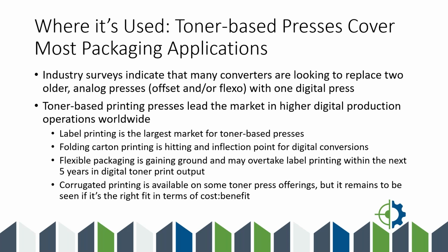The unique thing is, though, with modern toner presses with this productivity, if you have 20 jobs from 20 different customers or multiple SKUs, you can pretty much gang all of those orders, turn on the press, and it will flag and separate each job with a barcode or a marker for an operator to separate the prints. Once you turn it on, you can pretty much run an entire master roll if you've got enough to fill that in a single run where everything is separated. So all of those factors go into the cost benefit when you're looking at toner versus analog.